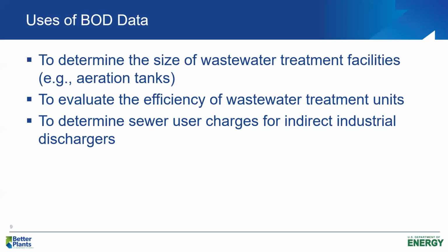We'll use BOD to determine efficiency of plants, and then we also use it to charge our industries if they discharge high strength organic wastewater into the sewer system. For example, in Memphis, we've got one industry that discharges about 150,000 pounds a day of BOD to the Memphis sewer system. That industry by itself, in terms of BOD load, is equivalent to a city of 750,000 people by itself.